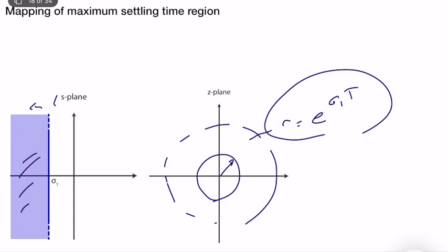So we are covering all of the frequencies, but the magnitude of the pole is decreasing, going along the negative axis. So it is staying strictly inside the small circle here. In general, we want our poles to stay in a safe region where we have a stable but relatively good transient performance.